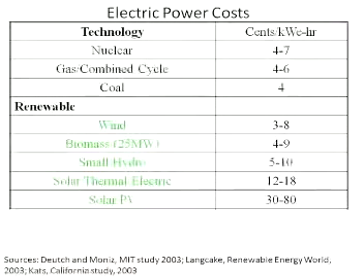That's without government subsidy. That's just basically taking the initial capital cost and then prorating it over the life of the PV, asking how many kilowatt hours we can generate from the PV, and placing the capital cost against this amount of generation. So right now, solar PV does not look economically competitive compared to the others. That's not saying that won't change in the future, and there's certainly a lot of research trying to reduce the manufacturing costs for that. We can also compare this with the cost of saving a kilowatt hour.